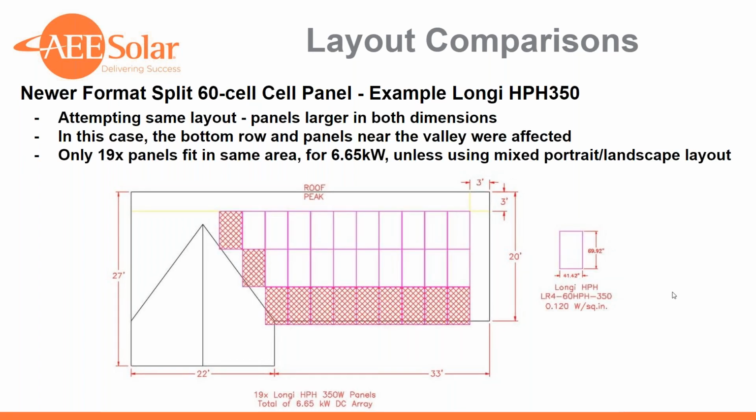Let's see what this longer one looks like. Here's the first example of trade-offs. Working down from the roof with this 3-foot setback, we're not able to squeeze in this third row of portrait. We did not cherry pick this roof. This is just kind of an unfortunate output. This is an instance where you would most likely be required to do this roof in landscape orientation, and there's nothing wrong with that.